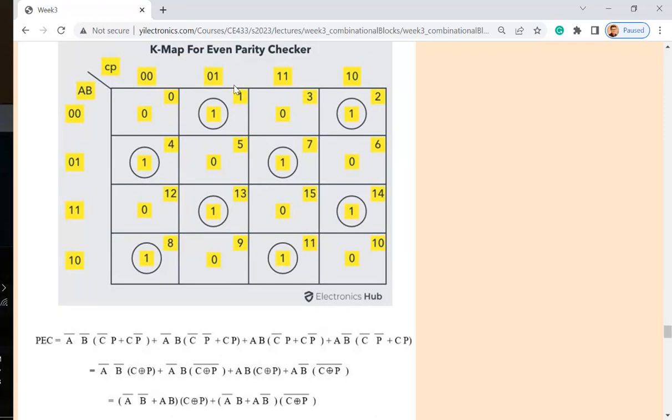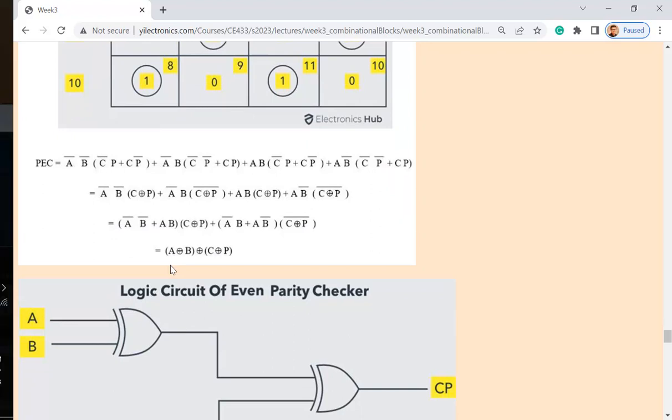Make sense? But you can see that the logic here looks shorter. Is that getting simplified? No. You're just changing the operators. You're changing the OR and NOT to XOR. What is XOR? One XOR gate has how many gates in there? Like 4 or 5, right? So we're not simplifying anything. It's just simplifying the look of the equation.